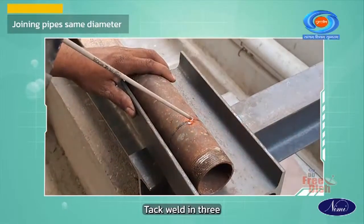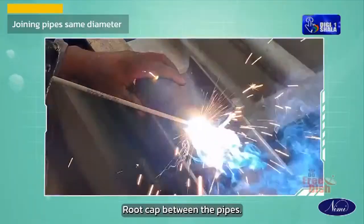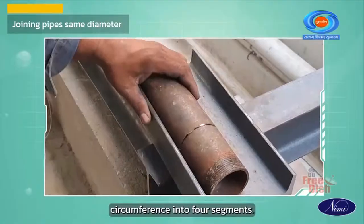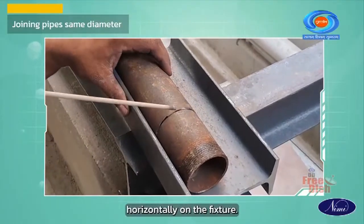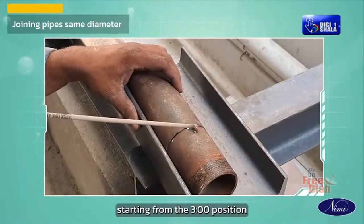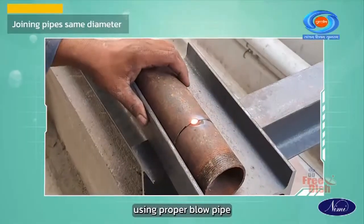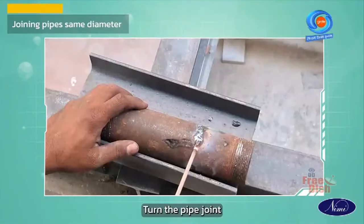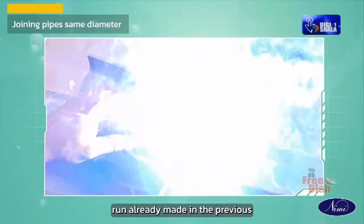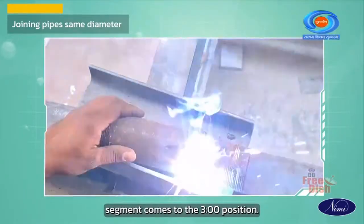Tack weld in 3 places, keeping 1.5 mm root gap between the pipes. Divide the pipe circumference into 4 segments. Keep the pipe horizontally on the fixture. Deposit the root run starting from the 3 o'clock position to 12 o'clock position using proper blowpipe and filler rod angles. Turn the pipe joint into the clockwise direction so that the end of the root run already made in the previous segment comes to the 3 o'clock position.